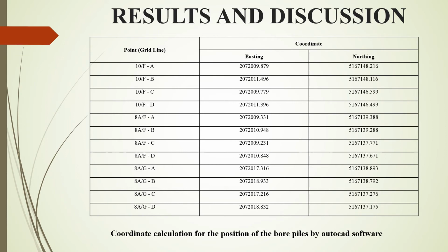By calculating the bearing and distance from at least 3 ground control points to each design setting up point, this is known as setting up by polar coordinates. The ground control points should be located throughout the site so that all the design points can be fixed from at least 2 or 3 of them, so that the work can be independently checked.